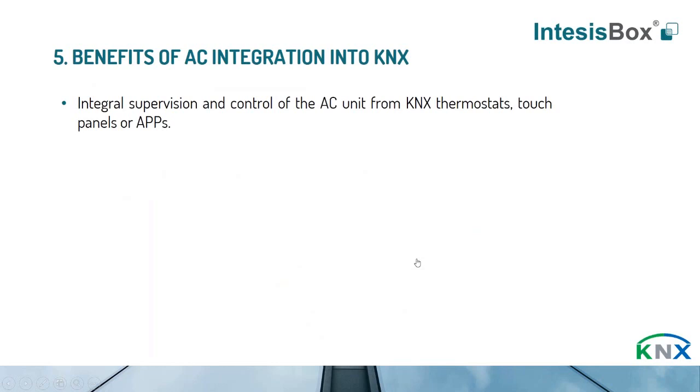Just to mention some benefits of integrating these AC units into KNX, we can have integral supervision and control of the AC unit from KNX thermostats, touch panels, or apps. As I mentioned, it is not an easy thing because every manufacturer is using a different protocol, and to have this integral supervision in KNX is really an important and really good point.